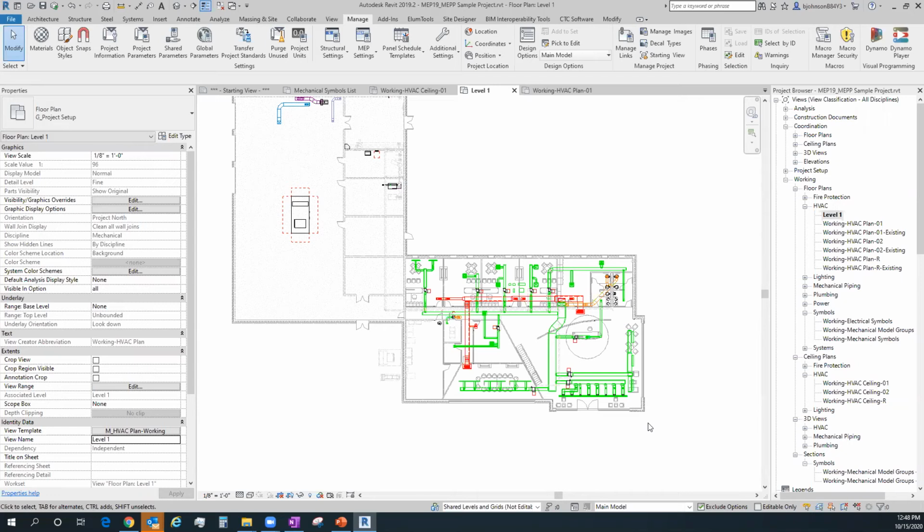So little things like that I have picked up over time, so I'd prefer to rebuild my template on every new version, especially when Autodesk does something substantial to that version. There's a couple of new things in 2020 and 2021 for the MEP side. There's some new analytics for building energy modeling within the HVAC side. So if I didn't start from a 2021 template, chances are I'd be missing something that it might need. And if I get a file corruption when I try to run those tools, chances are I just have a bad template. So again, areas of concern, whether that's the true cause or not, that's something that's debatable, right?